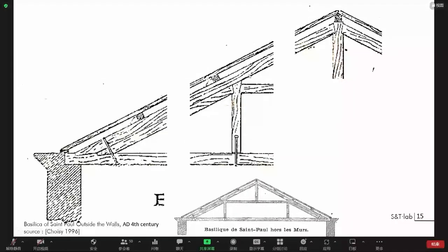That's a question of the joints, the connection between bars. And if you are looking carefully at this, you see that the geometry of this connection is designed to develop a certain kind of transfer of forces. So if you are pushing here at the head of the structure, you see that the way that the notches are made into the central piece of timber will transmit forces in compression, and that those connections are studied also in that way at the basis of the structure.